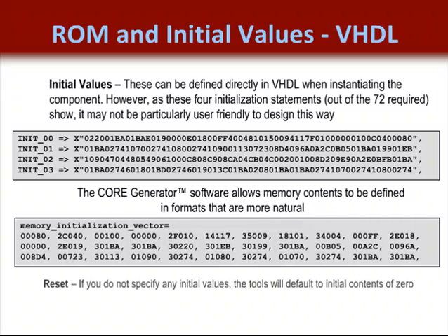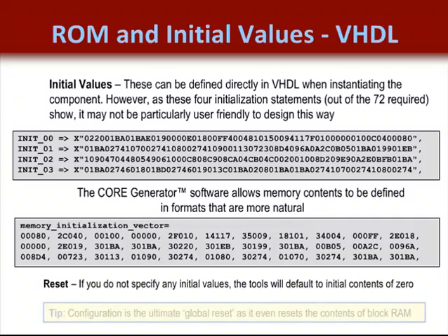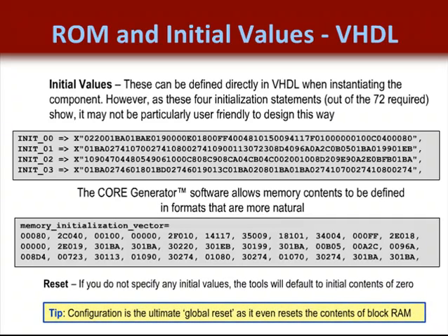You should know that if you don't initialize the block RAM, it will come out of configuration with initial contents of 0. So in this case, a reset would not be necessary. This is interesting because if we get in the habit of inferring the appropriate register, we can program the flip-flops to come out of configuration initialized to a particular state without using a global reset. So keep this in mind, because the more resets you avoid building, the more efficient and fast your design will operate.